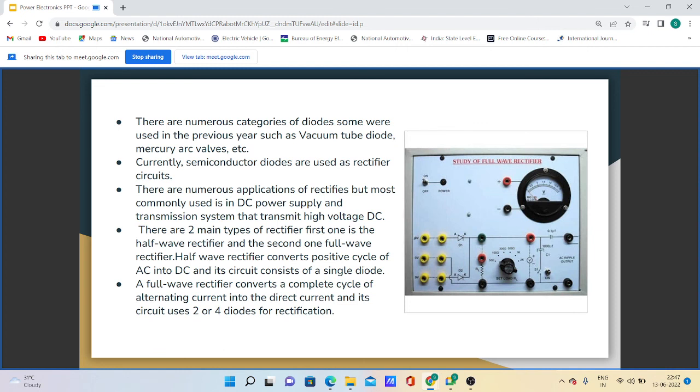Other devices that have controlled electrodes as well as acting as unidirectional current valves are used where more than simple rectification is required. For example, where variable output voltage is needed, high power rectifiers such as those used in high voltage direct current power transmission employ silicon semiconductor devices of various types. These are the thyristor or other controlled switching solid state switches, which effectively function as diodes to pass current in only one direction.